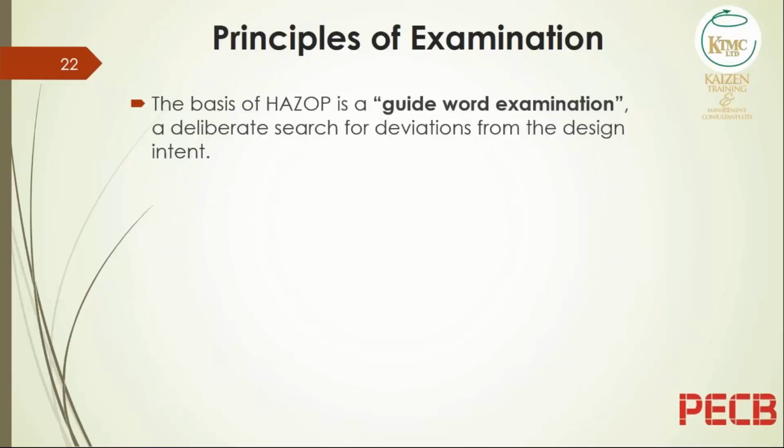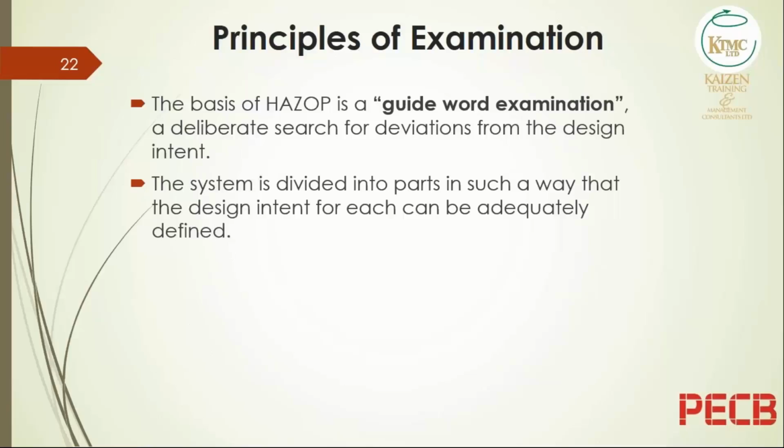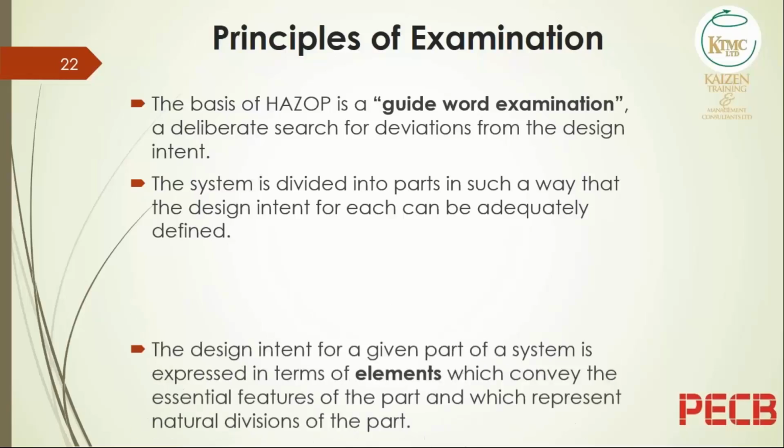So the basis of HAZOP is a guide word examination, applying guide words to the system. It is a deliberate search for possible deviation from the design intent. We understand that the system is divided into parts in such a way that it can be systematically and logically examined.